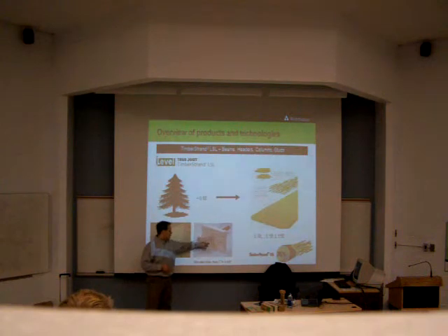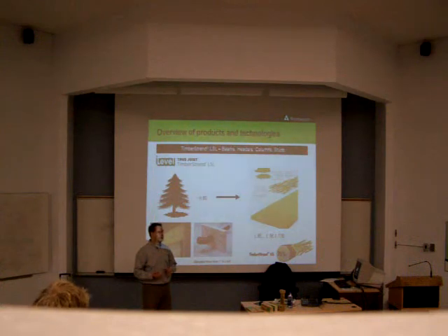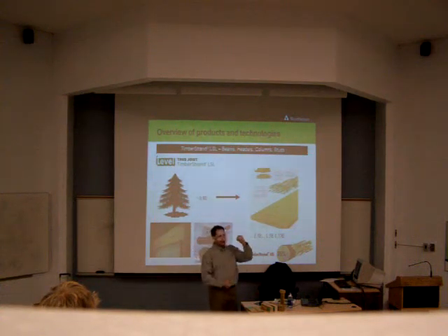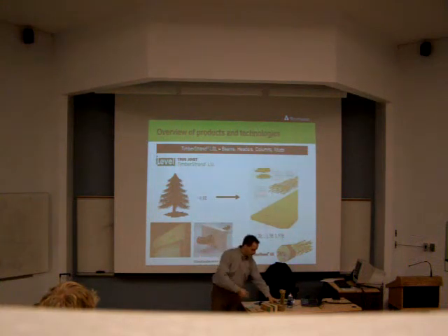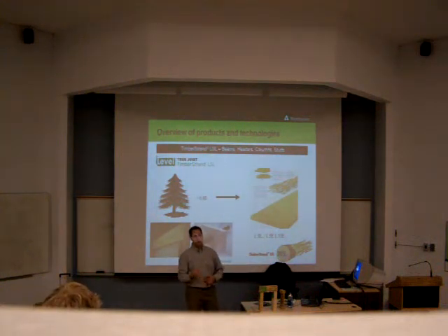You'll see here what's special about timber strand. It's the only beam on the market that you can cut large holes in. And that's because of the design properties. It has a lower E value, but it has a much higher strength in other design properties, such as shear, the effect of wanting to slice off at the support. So if I have two walls here and I have a beam from point A to point B, and there's a lot of load, at the support point I'm wanting to shear off, timber strand performs very, very well. It has a lot of shear strength, more than other beams on the market.